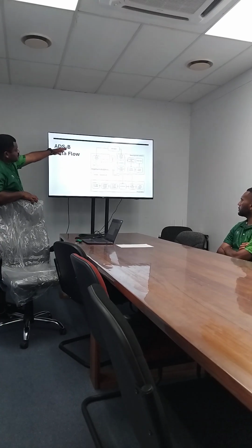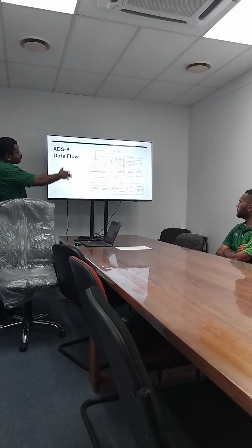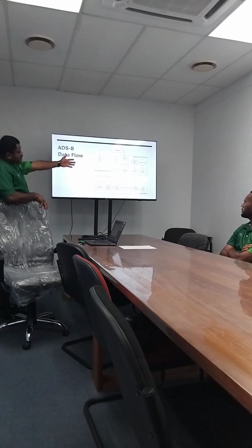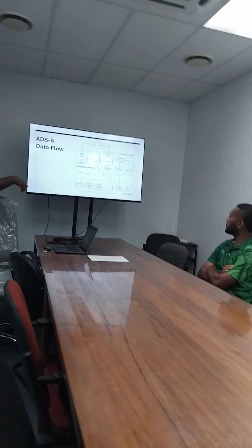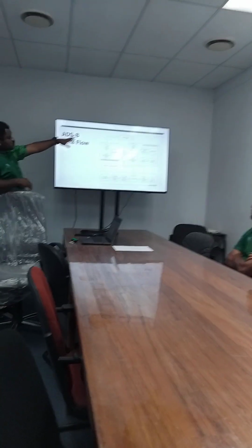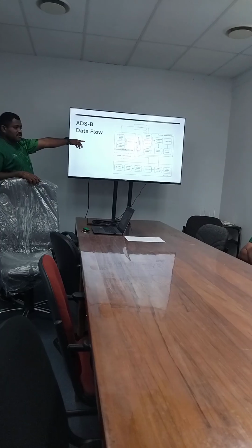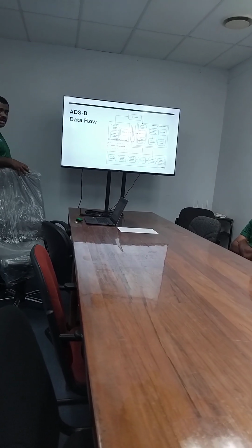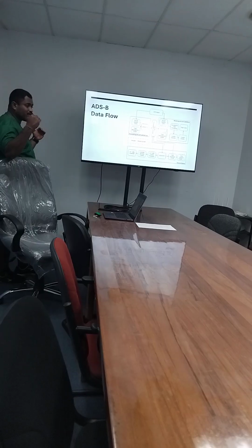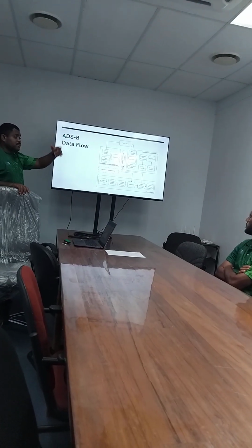On the receiving aircraft, that's basically the cockpit. You see the ADSB receiver on the aircraft. It goes to the FMS of the aircraft, along with data collected from aircraft sensors and GPS, goes to the surveillance data processor, and goes to conflict detection. Basically, if two aircraft are nearly colliding, the alerting system will highlight in red that there's an aircraft or something close by. That's the purpose of ADSB out. That's the purpose of ADSB data.